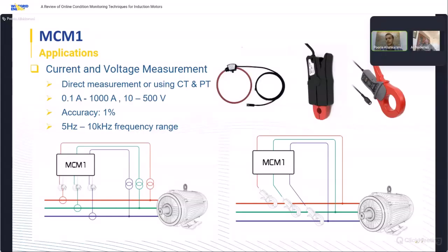For example, a broken rotor bar usually causes an increase at 49.5 or 50.5 hertz. So gathering the data for around 10 or 30 seconds will allow us to detect these parts. That's for the broken rotor case.